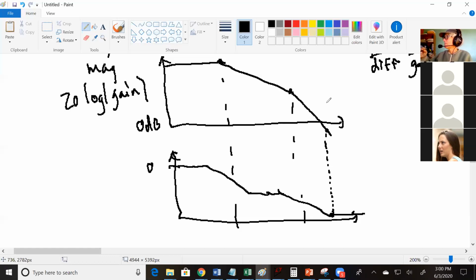Now the signal getting fed back is actually bigger than your input. But if at 180 degrees phase shift you're less than 0 dB, in other words, the signal getting fed back is much smaller than your input, then who cares? We can ignore it. So by Barkhausen's criteria, this circuit is okay, because at 180 degrees phase shift, your gain is less than 0 dB.